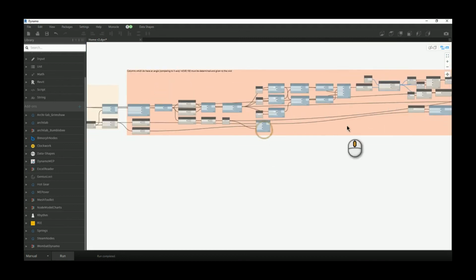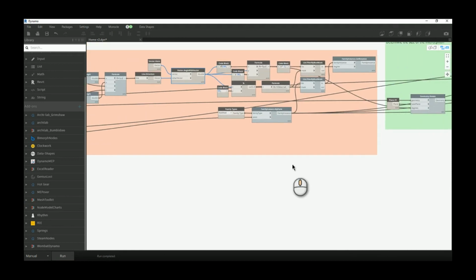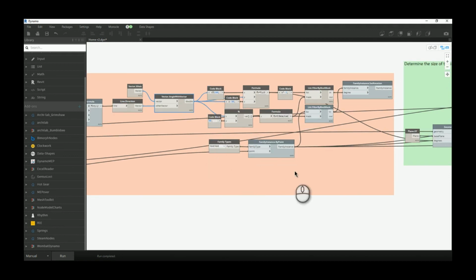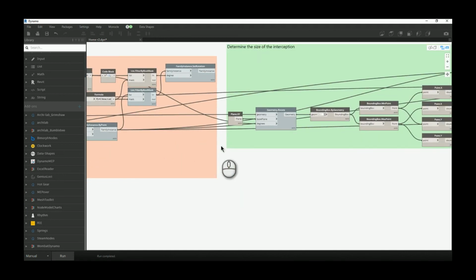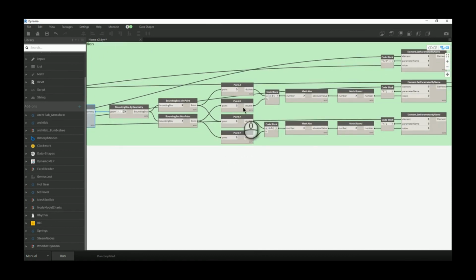As we said previously, this part over here is basically the part in which we need to determine the location for the void. So now we did determine that there is no need to perform rotation for the voids. We just place them correctly by the x, y, and z coordinates. If you have some rotation of the wall like we did have in the first example, you will again rotate only those solid parts inside Dynamo, transfer all that to the bounding box, find the minimal and maximum point. From that point, again, you will easily receive the information regarding the size.